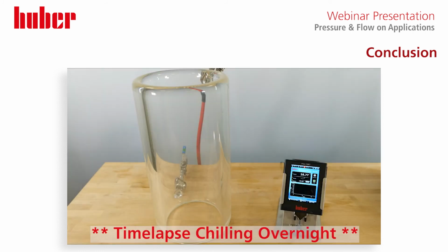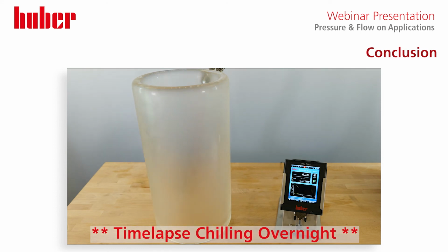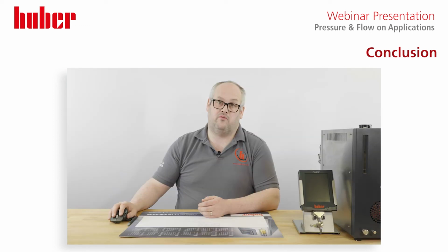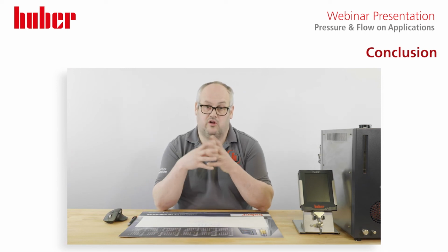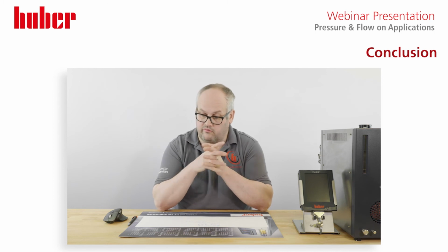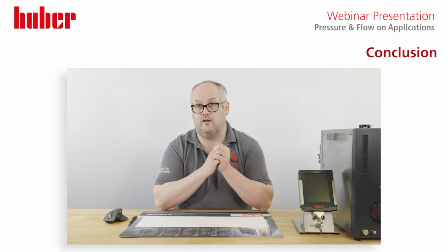And what we've done is we've actually chilled it down to -14, so that we've got a nice starting temperature. We don't have to go crazy. I don't have to go -80. I reckon if I go from -14 to 0 degrees C, that'll be enough to cause issues with our reactor system. So if we think about the temperature range that we're actually going to work over, how much will our thermal fluid expand going from -14 to 0 degrees C?